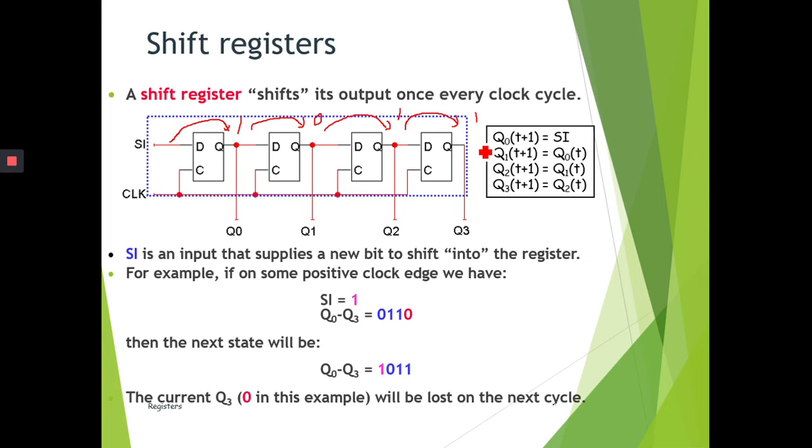Alright, so what happened is that the value on the most right here will be gone in the next cycle. You can see here 0 is now gone in the next cycle. The new value, which is 1, is waiting at the signal input here. It's being moved into this 4-bit data.